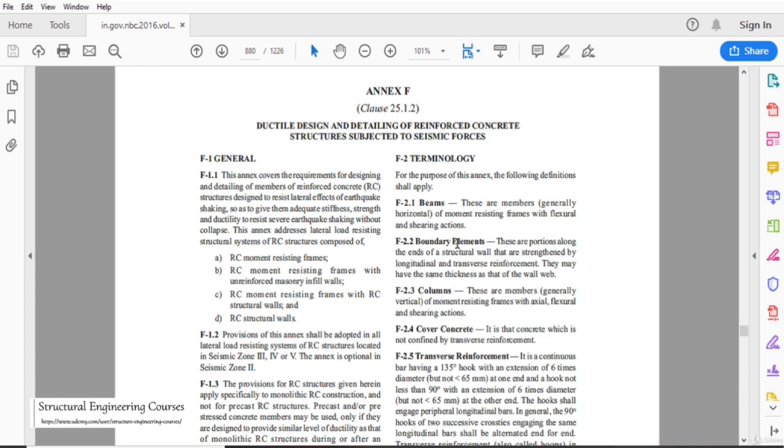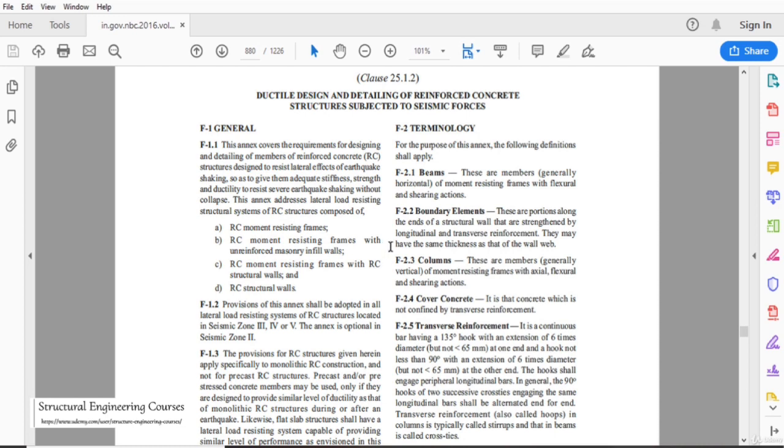Only the reinforcement, or the reinforcement in the joints that we shall provide, can behave as seismic joints, and that can only be a safety factor for the structure, for the formation of hinges and releasing of energy, and for the structure not to collapse. So to avoid the structure collapsing in seismic zones, we do need to do the seismic detailing. So you can refer to IS 13920, released in the year 2016, latest amendment.